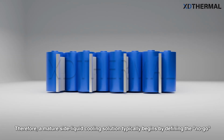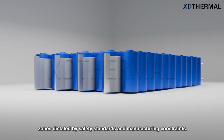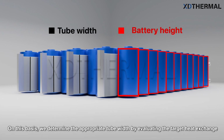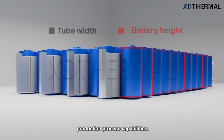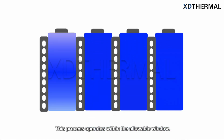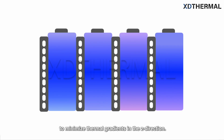Therefore, a mature side liquid cooling solution typically begins by defining the no-go zones dictated by safety standards and manufacturing constraints. On this basis, we determine the appropriate tube width by evaluating the target heat exchange capacity, estimating the effective contact area, and integrating coolant flow rates with production process capabilities. This process operates within the allowable window. Through calculations, prototyping, and testing, we maximize the flat tube's effective coverage to minimize thermal gradients in the Z direction.